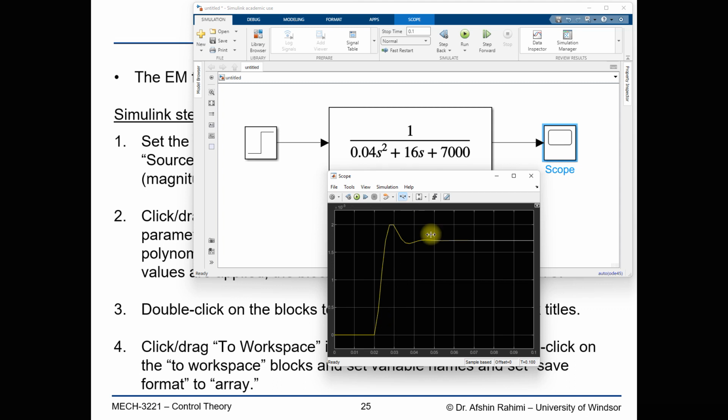This is because we have not changed any properties from the Simulink model to have indicated step sizes that are fine enough or small enough that give us a smooth trend line. Because we haven't, Simulink is deciding on that step size automatically, and that value, it seems, is not small enough for us to capture properly the behavior of this system output.